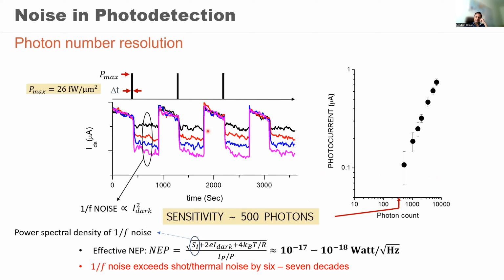Now, when the electron is coming to graphene, it can recombine in MoS2 itself, and that can generate some noise, isn't it? Yeah, right. Very good. So what I was trying to say, that's precisely the mechanism we are able to suppress. Absolutely right. If the electron can jump back into MoS2 and essentially recombine with the hole which is there, then you can create noise. But those time scales are far faster.